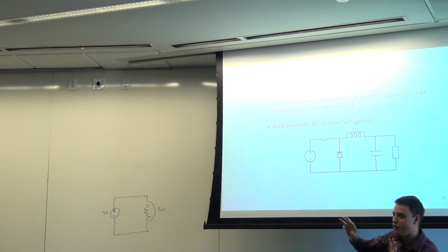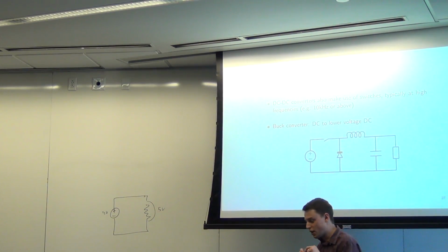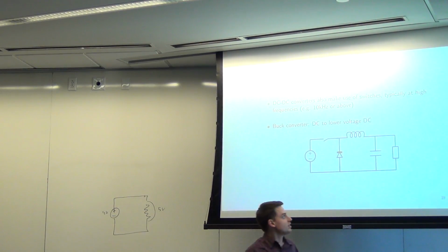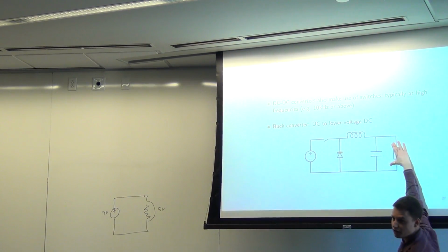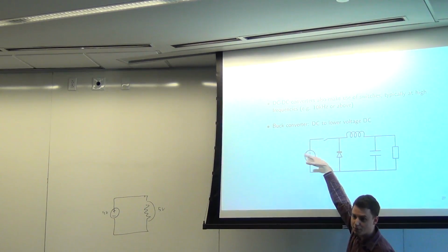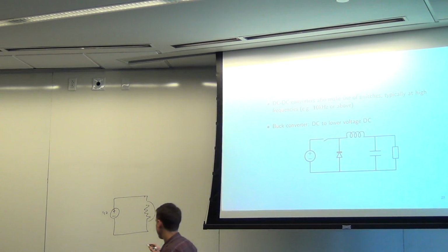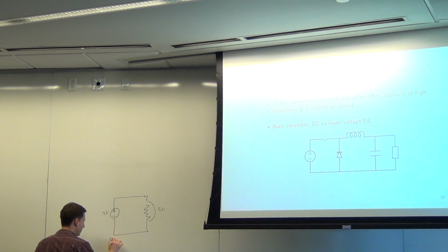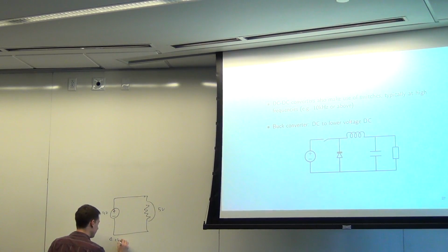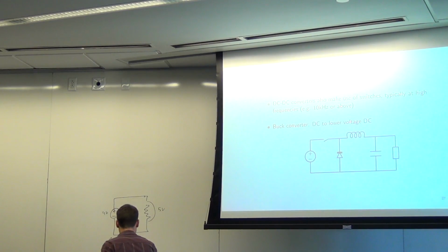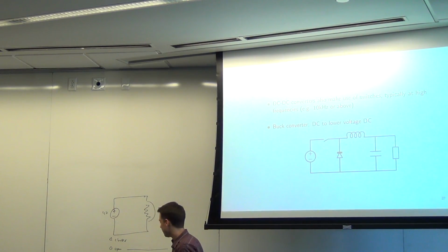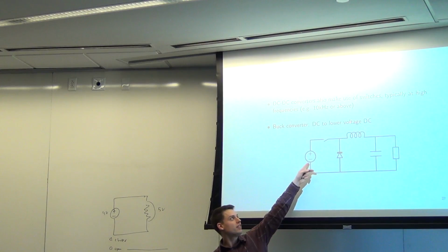So this is sort of confusing, but essentially if you write down what's going on, integrate these equations and smooth it out, what you'll see is that on average, the voltage you see here is just going to be equal to the proportion of time the switch is open versus closed. So if you send a signal like this to the switch, where 1 will be closed and 0 will be open. Again, if it was always open, that would be 0 voltage. If it was always closed, it would be whatever voltage you see there.